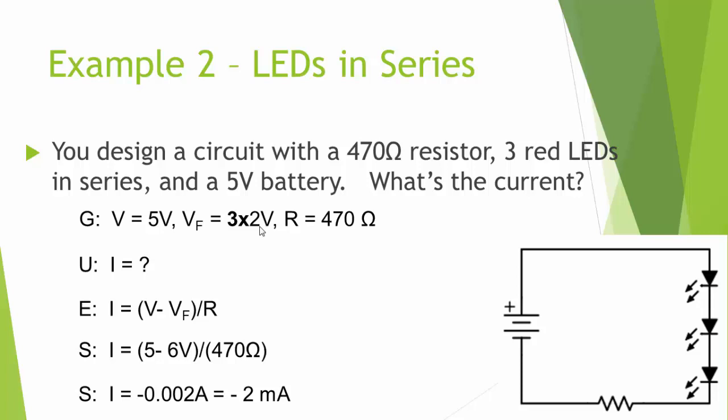Well, wait a second. Negative? Well, we talked about previously that just means the current's going to flow in the opposite direction. Well, we need to remember these are diodes. Current can't flow in the opposite direction. In fact, what will happen is we'll see zero current here.